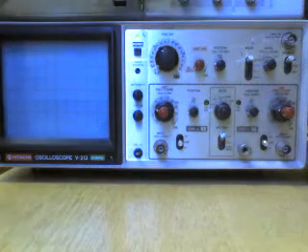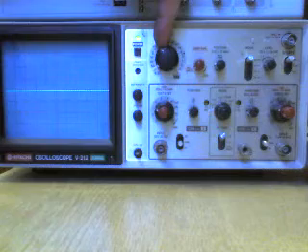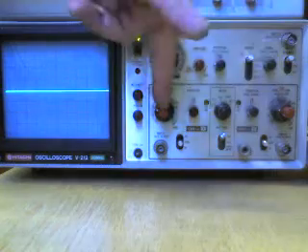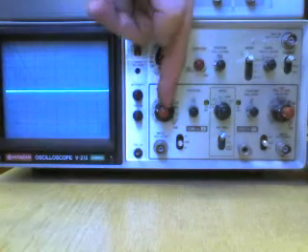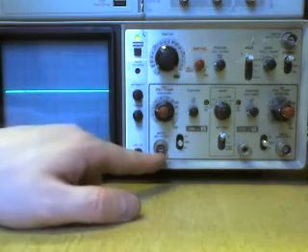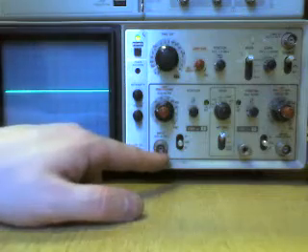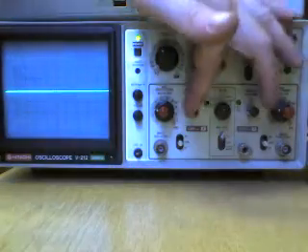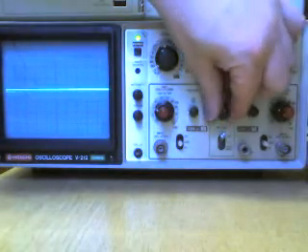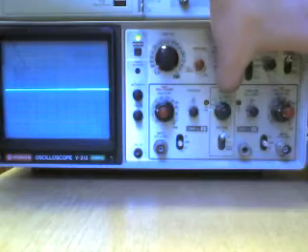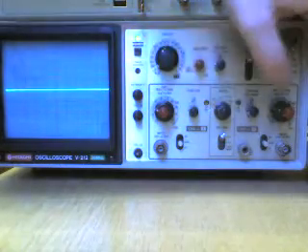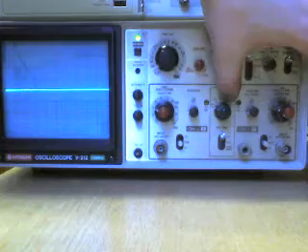Okay, just to introduce you to the front panel, we have time per division up the top here. We have volts per division knobs here, and the reason why we have 2 volts per division knobs is because we have 2 inputs. You can actually measure 2 waveforms at the same time on this oscilloscope. Right then, we have coupling for channel 1, coupling for channel 2. Little knob for telling us what mode we're going to use, so you can either measure channel 1, channel 2, or we can add them together, or we can look at them at the same time.